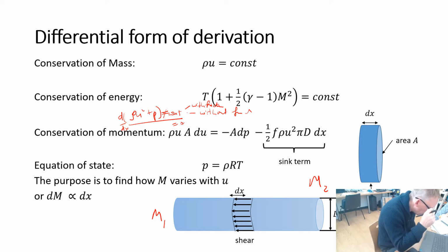It's a little bit more subtle than that because of the way the analysis is derived; there are subtleties in how changes in area are accounted for or not accounted for. So this is really what we call a long wave approximation: the pipe cross-section area changes very smoothly with distance.